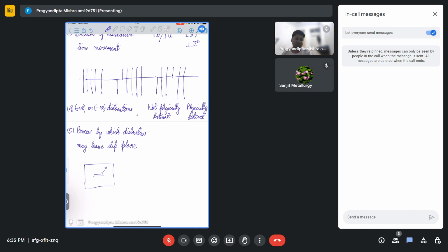So in edge dislocations, what has been observed is that they usually climb, while screw dislocation will cause cross slip. Okay, so this is the way they leave that particular slip plane. So this is a property of the dislocation, but whenever you are looking at any real life examples of dislocation, because they show mixed characteristics, they will sometimes climb, sometimes cross slip, depending on which is feasible or which is essentially leading to them reaching a lower energy, right? Because they're trying to minimize the energy.